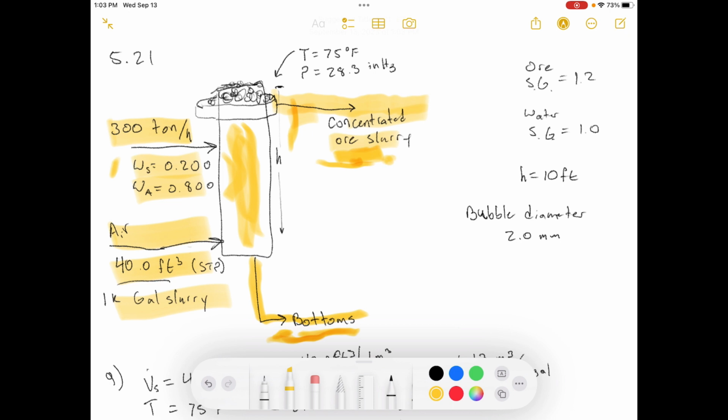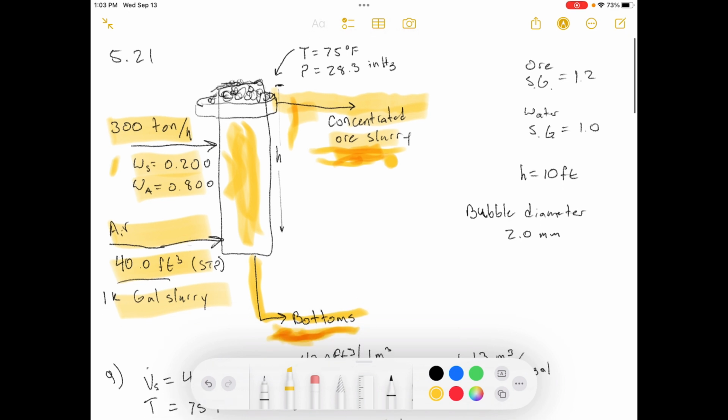But yeah, you do have solids and you have water coming out the bottom and the top, but the part of the solid that you want is going to come out the top. That's the purpose of this unit, to concentrate the solids that you want and remove the solids that you don't. So in copper ore, typically you bind the copper to the bubbles, and they come out the top, and in the bottoms you get the clay and other junk solids that you don't need. They call it, I think, tails. If you ever see tailings piles at mines, that's what is coming out the bottom.